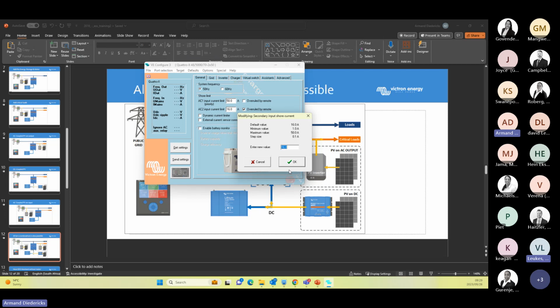So calculate the sizing of your generator, do the Ohm's law, see if it's an 8 or 10 kVA generator, then select a 10 kVA system, 40 amps, it's fine, ideal. If it's a 5, it can ideally provide you with 25, but put 16 or 20 amp, then it will allow the generator to provide power without the AVR fluctuating too much.